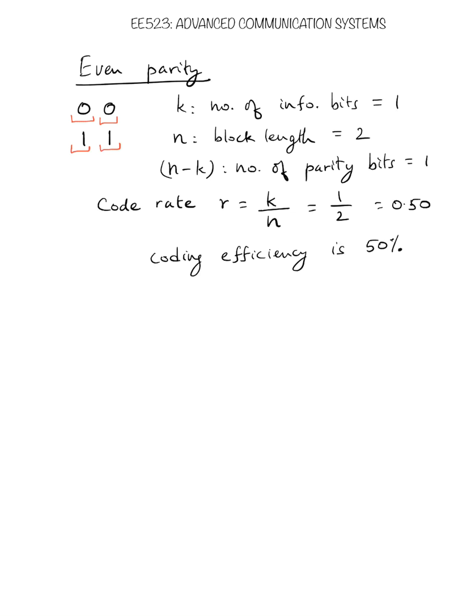That means for every bit we are adding one protection bit. This extra bit is not part of the information, so for the end user it will be discarded, but the transmission cost includes the cost for transmitting both bits. So out of 2 bits, only one of them is the useful bit for the end user. So the coding efficiency is said to be 50%.